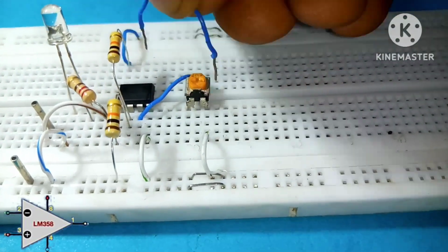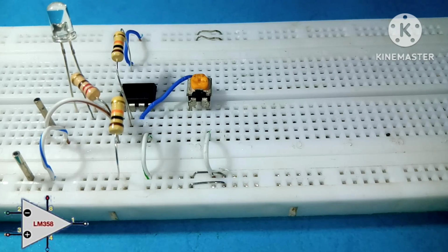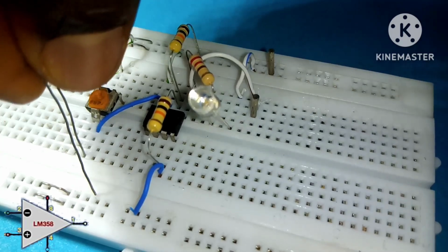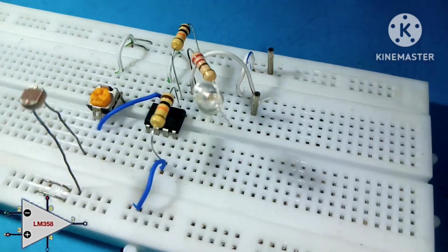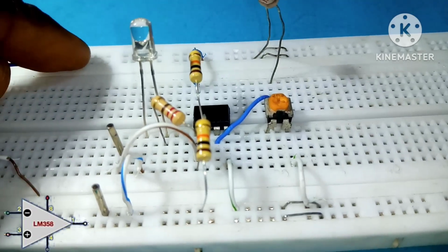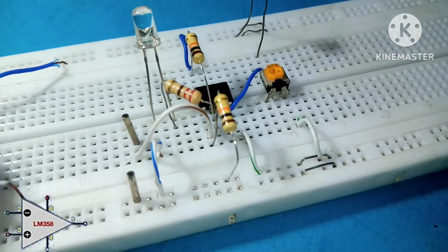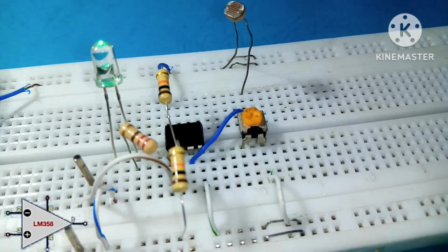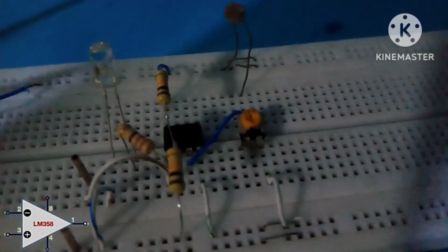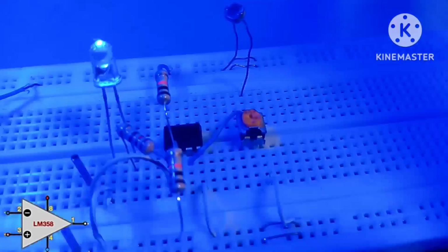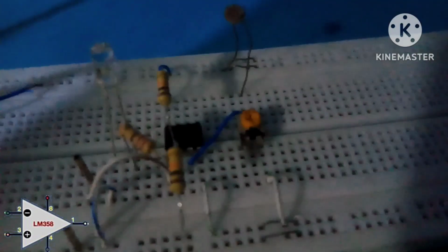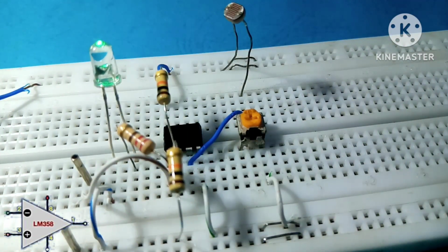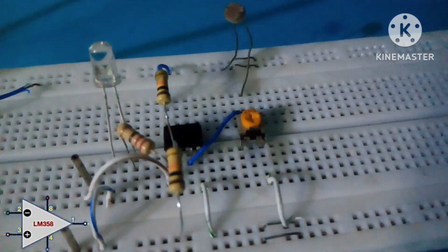So you're going to change the way we wire up the variable resistor. Place the LDR on the breadboard such that one of its leads is connected to the positive rail and one of its leads is connected to the middle lead of the variable resistor. And so we have our power supply inputs coming in, and we see our LED coming on because we have room light. If I switch off this light, our LED goes off immediately, and if I turn on the light again, the LED comes on, and goes off again when it detects the darkness, and still stays on with this light in the room.